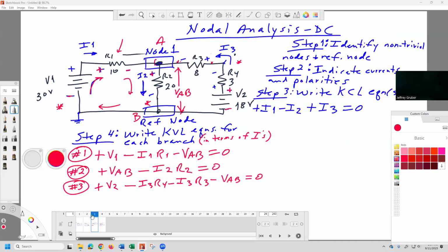I'm just going to point up all into the node. It'll be I1 plus I2 plus I3 equals 0. And he got the right answer. He just drew all the arrows pointing at the node. Because the direction of the arrow determines this right here.